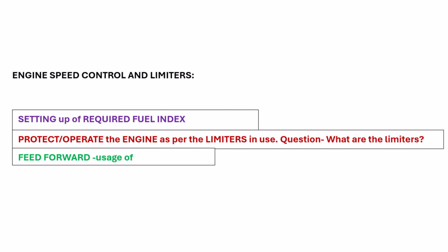And this amount of steam flow will be measured by the steam flow controller. When the steam flow controller measures that a large amount of steam is flowing, it knows the water level will probably be going down naturally because water is turning into steam. So before the water level controller tells the feed valve to open, this steam flow controller will send the signal and tell the feed control valve to open, even though the apparent level is higher. So feed water will start entering. So this is feed forward. All right.